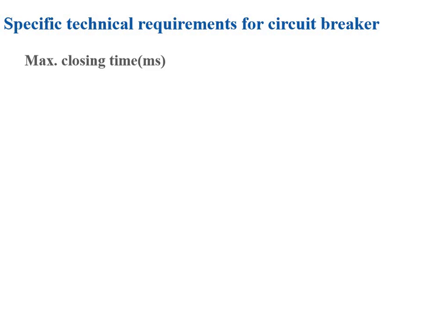Similarly, maximum total break time, so breaking time, and this is very important because this break time is there to isolate the faulty section from the healthy section. Closing time, in our hand, means when the system is healthy, then we close the circuit breaker contacts. But circuit breaker contacts are separated when there is a fault in the system